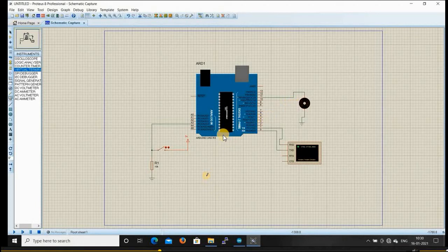For example, I fixed the time limit for 20 seconds. The power has gone at 10 seconds. Then the time is resumed at the 10th second, and later it will continue from the 10th second up to the 20th second. So the motor will be in on state only for 20 seconds even though we have a power loss. This is our second case.